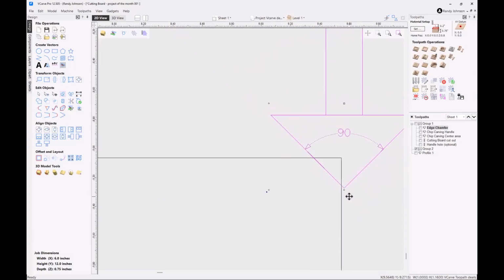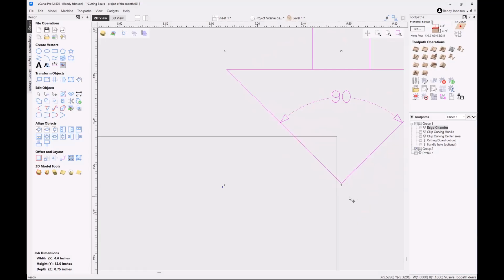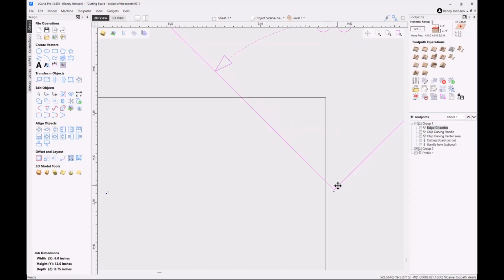The advantage is that sometimes if your material is a little bit off size, say my material is a little oversized, I'll end up with that little ridge right there. By doing it like this, it overcuts it and gives you a nice clean edge.